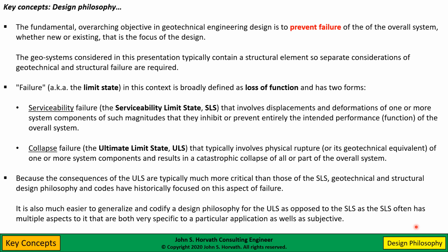For example, if you have a floor in a warehouse that is settling excessively, in terms of total and differential settlement, it's not all or nothing as to when that floor is usable or not. I've certainly been involved in looking at a number of case histories over the years where this sort of problem has come up, and it might be okay, we can't stock things as high as we used to on the floor, but we can still use it to some extent.